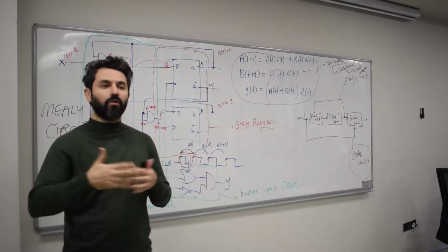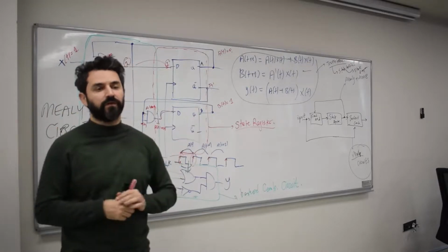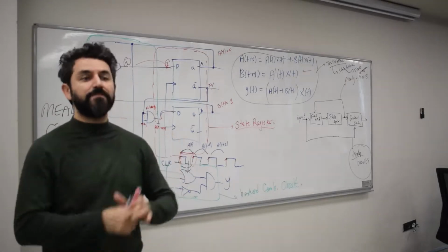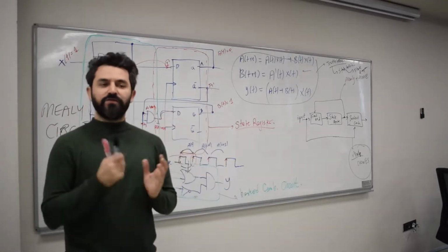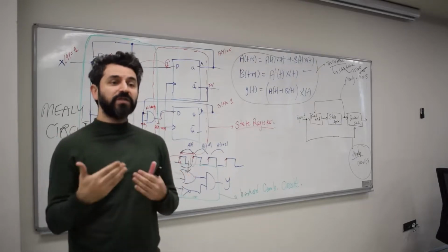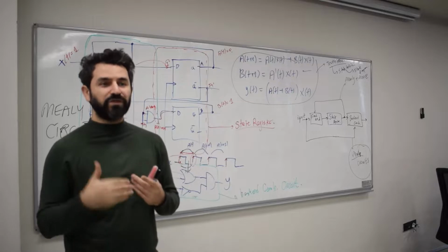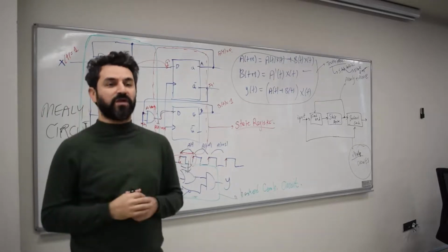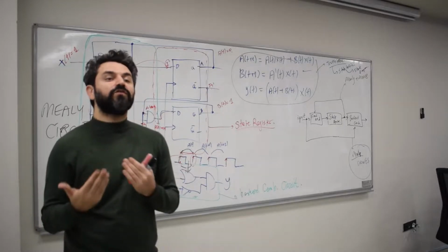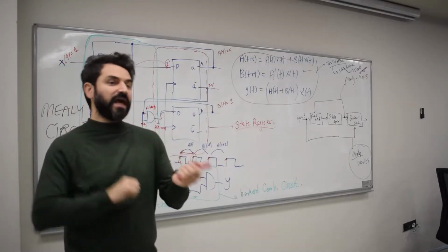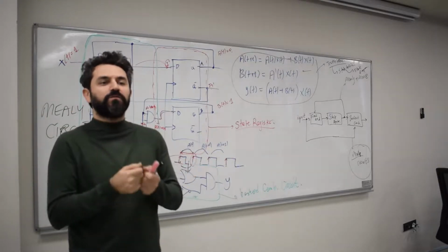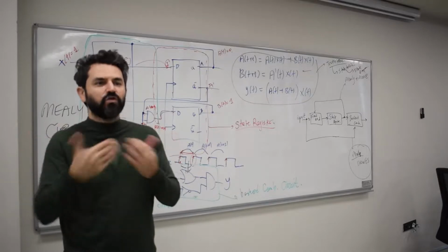Okay, the digits are all ones because it's a black screen. So I send you all the time 1, 1, 1, 1, 1, 1, maybe millions of times. At the receiver, you're getting those ones, but at some point, the communication systems use those bits to synchronize itself with the transmitter. Since there is no zero in that synchronization information, because of the jitter, delay, and other environmental conditions, that jitter would be accumulated because there is no zero, right?